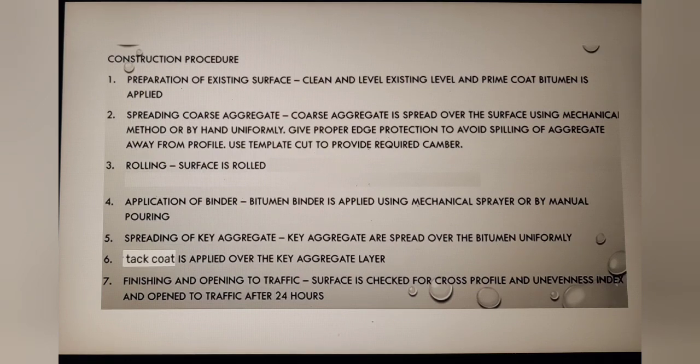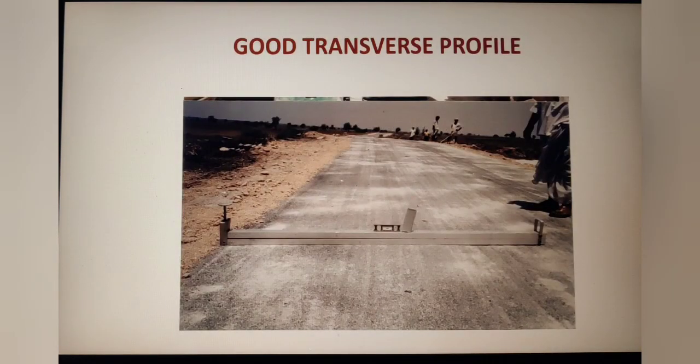Seventh step is finishing and opening to the traffic. Surface is checked for the cross profile, unevenness index and opened to the traffic after 24 hours. So here this is the good transverse profile of the road.